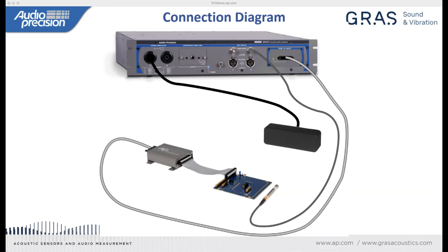So the little speaker I'm using, while quite good, isn't very useful below about 200 hertz. And probably I can't drive it to more than about 114 dBSPL near field. So what speaker would I choose if I was measuring another microphone?